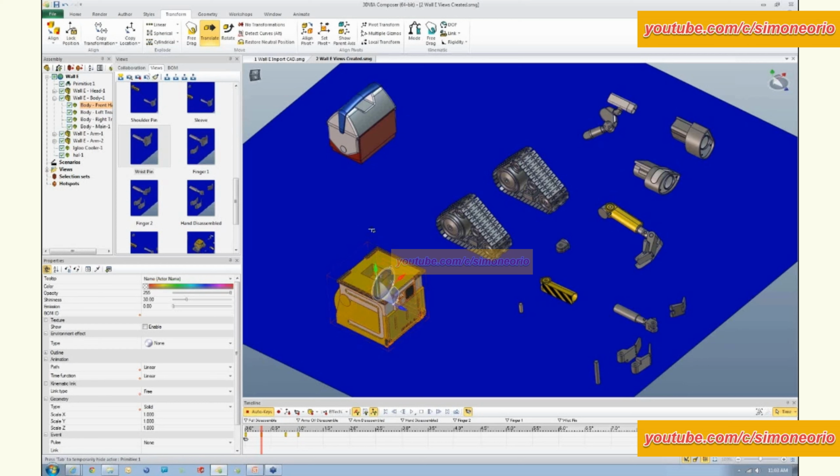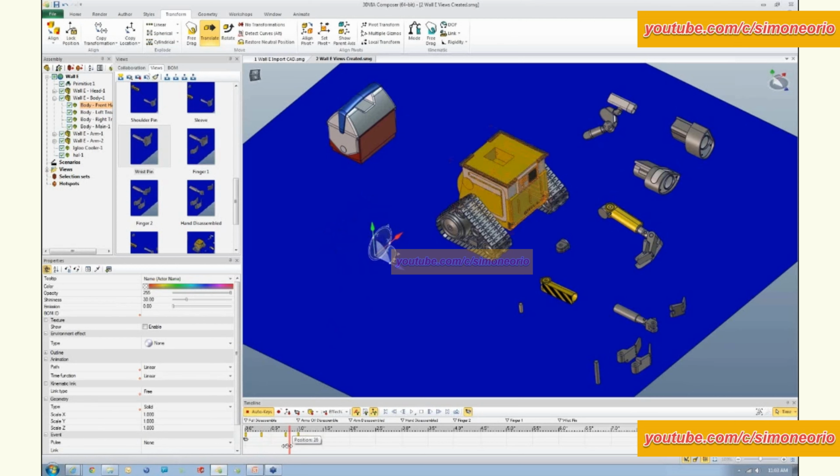With the webinar here, the response is really quite slow, so probably works good for you. That way I don't move too quickly. So now that second key, I've got its position set. Let's go over to the third key, and here I want to also overwrite the key that's currently in place. And so we'll just drag that up in the Y direction.